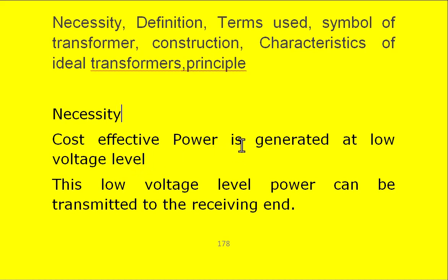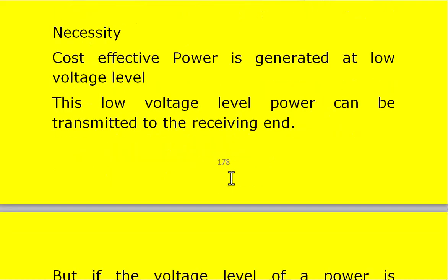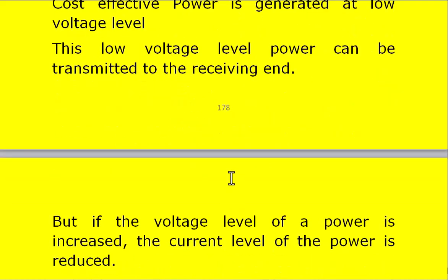Let me cover first what is the necessity of the transformer. In general, the power is generated at low voltage level. This power can be transmitted to the receiving end at low voltage level, but it requires large diameter conductor, which increases the capital cost of the power transmission.